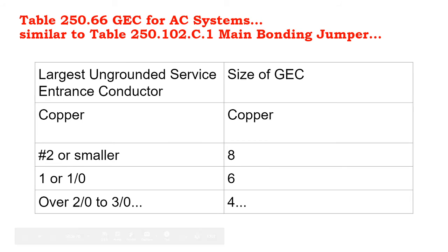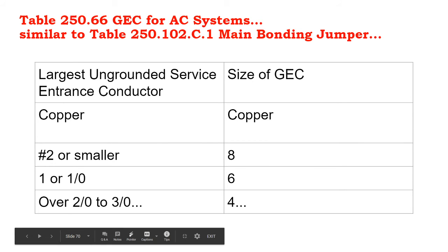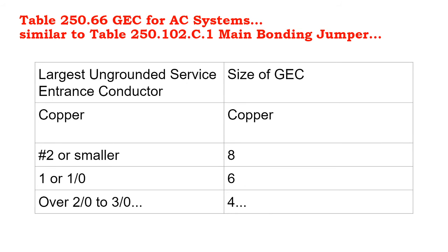Depending on the size of your electric service, you can have really small equipment grounds, but the smallest is number 8. For solar, whatever size of ground you need to run up to the rooftop, the smallest size is number 8.